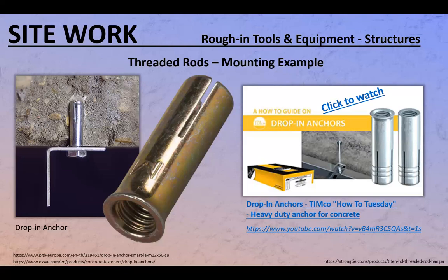Then what you do is you do the punch. You insert the punch in there, and you can use a hammer to expand those wings, and then it stays. Sometimes you get an attachment to the hammer drill. So instead of using your hammer, because if you have 1, 2, or 5, that's fine. But if you have like 200 or 300 of those to make, you want to make the job as easy and as efficient as possible, so you don't get injured from prolonged doing of a certain type of task, right?